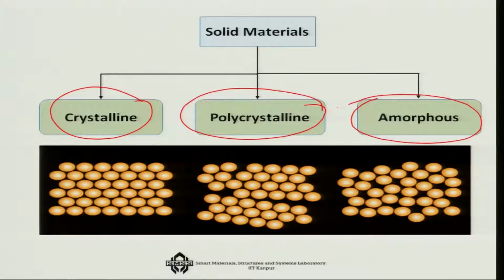So, why do we use X-ray for these diffraction techniques? It is because the wavelength of the X-ray typically matches the crystal plane separation distance, which is in that 1 to 100 angstrom kind of range, and hence X-ray can be used to resolve this picture. Sir Bragg and his father are the people who got the Nobel Prize in this direction.